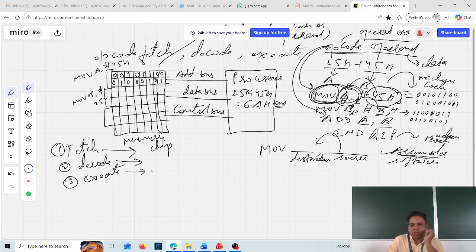So in this case, this instruction will be fetched inside the processor. Now one more thing is that each location has a certain address. For example, this may have address 0000H, the next may have address 0001H, 0002H, 0003H. These are hexadecimal numbers which are 16-bit.